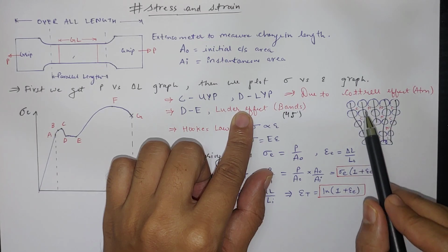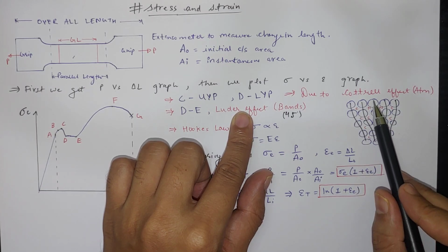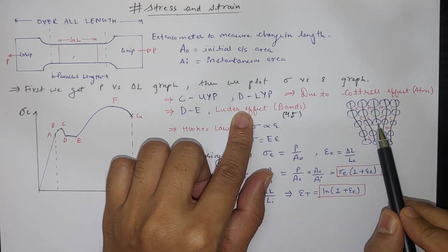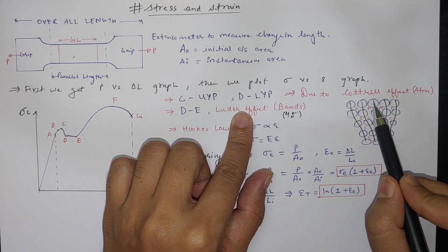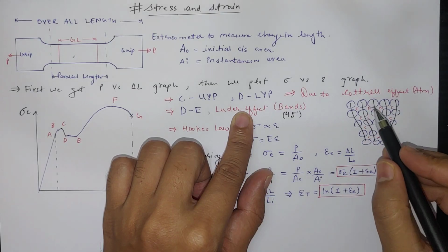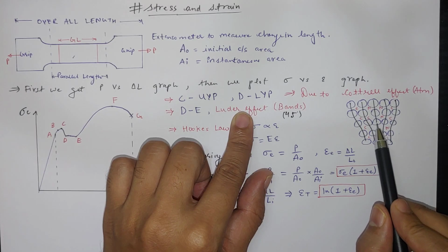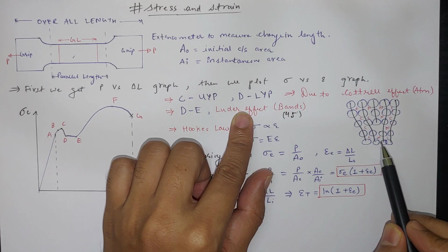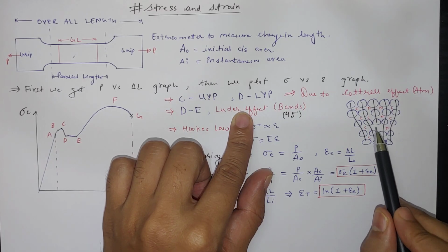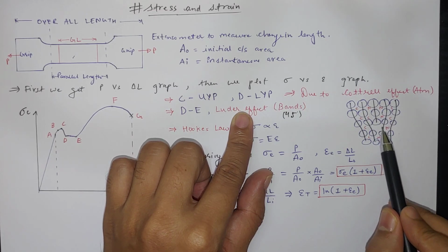Now if you draw these lines, we see there is a line or edge dislocation which goes inside the plane. So this is inside the full plane of atoms which has a dislocation here. These are the entire planes, but this is a half plane, and here there is a void, meaning a bigger space is available.